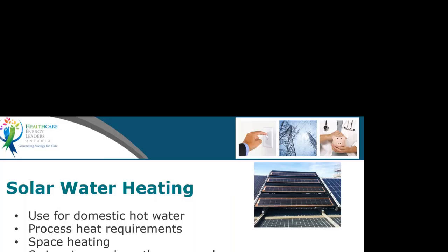So in solar water heating, we've got a number of places we can use the heat that we generate from these things. We can use it for hot water, could be used for process. Some solar water heaters, here's an example. I'm just going to go in my office and pick up this, which is actually an evacuated tube solar collector. This actually is a flat plate inside a vacuum tube with a heat pipe basically inside it, which transfers heat up to this device up here, which would be a copper pipe carrying your heated liquid, and then that's how you thermally couple it to the solar tube.